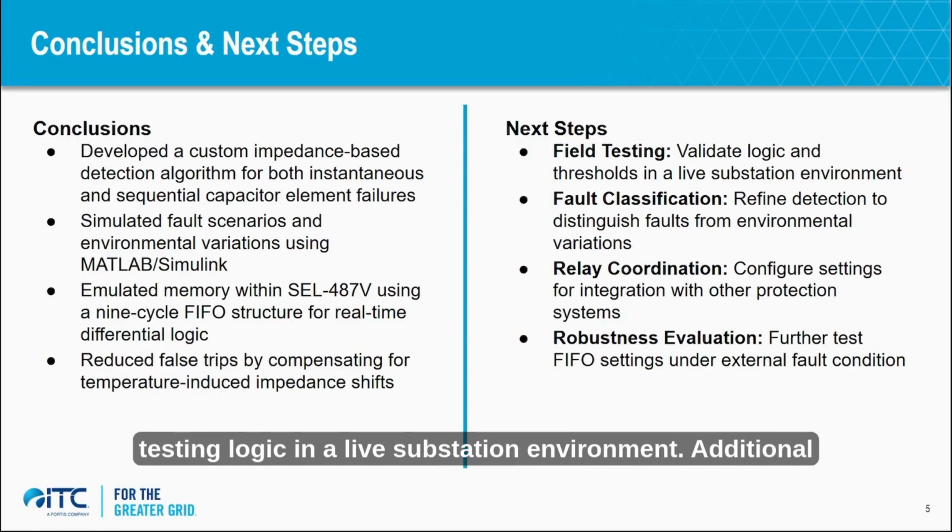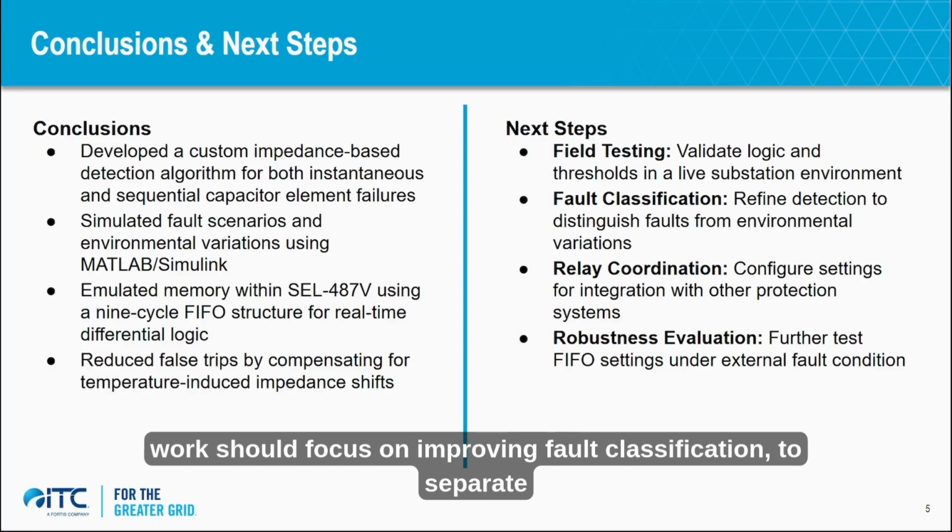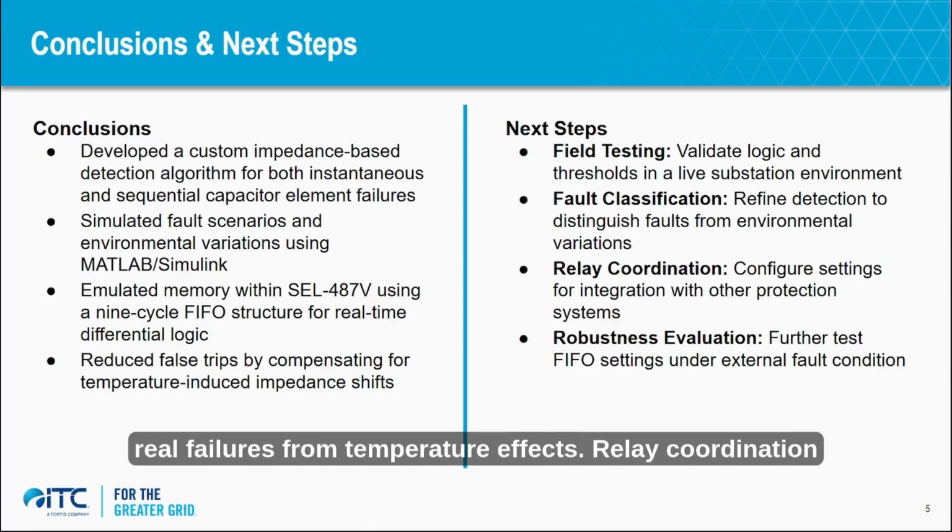Looking ahead, we recommend testing the logic in a live substation environment. Additional work should focus on improving fault classification, separating real failures from temperature effects. Relay coordination settings should also be refined, along with further testing of the FIFO logic under external fault conditions.